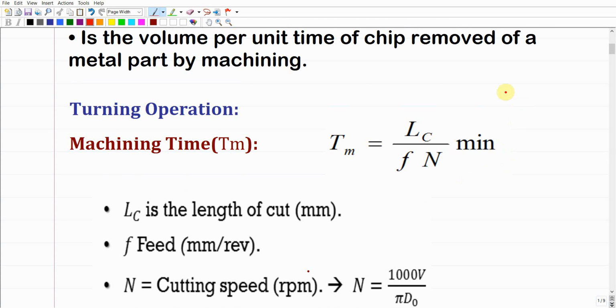So just a quick review of the operating principle of the turning operation, as we mentioned before. You're going to have a rotating work part, assuming that this is the axis of rotation, and you're going to use here a cutting tool. This tool is just going to be moving parallel to the axis of rotation. So this definitely is going to give us the feed motion, and the rotation of the work bar is going to give us the cutting motion as we discussed before, right?